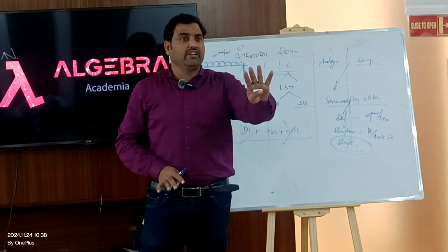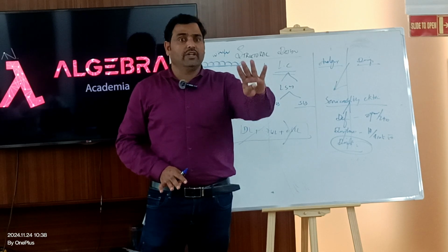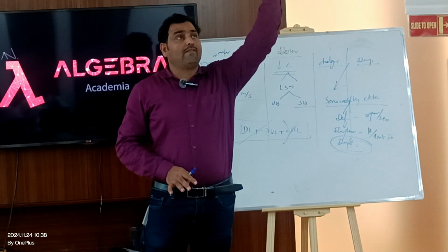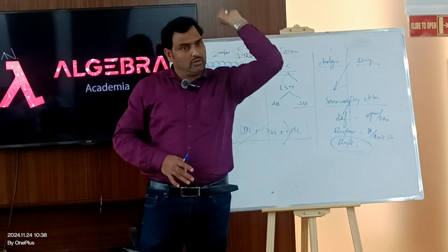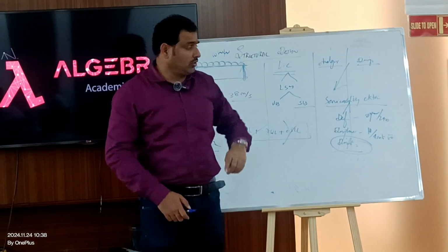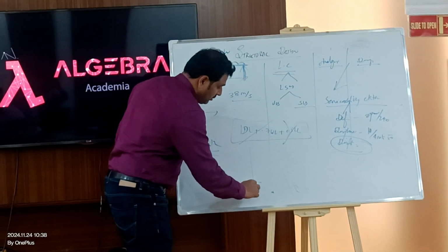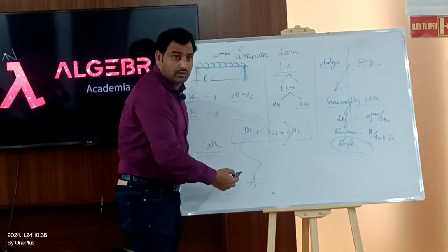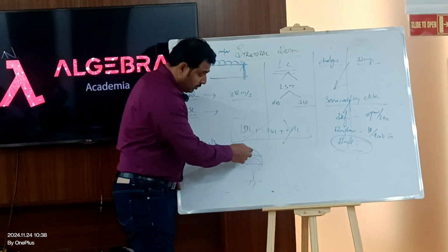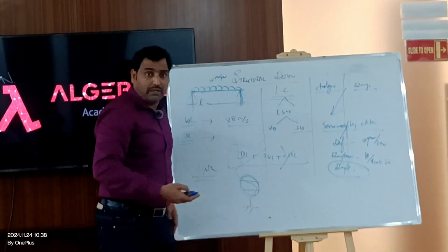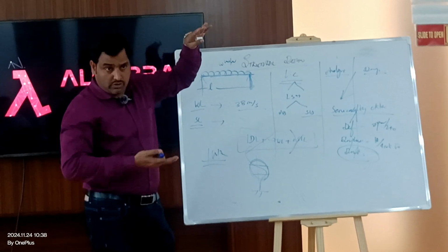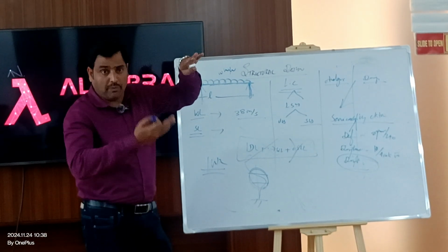Because where is the wind going to be higher? Only on the top. If I have beams on the top floor, the wind will be countered. But it's not like drift. Drift will have a variation, might be 2/3, might be 3/4. If it is 2/3, 3/4, it will be governed like the majority of the floors, might be 6, 7, 8 floors. So around 8, 9 floors I cannot provide the beams. They are very important. Might be it is all typical.